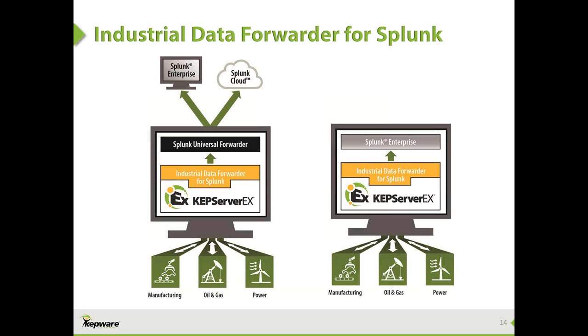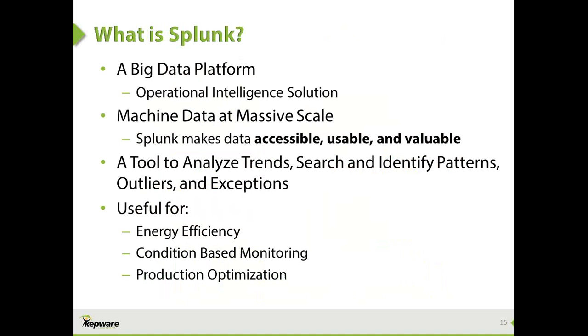So at this point, you're probably asking, well, what is this Splunk application anyway? Splunk is not part of KEPServerEX. It is another vendor, a third-party vendor that we're working with and collaborating with on this product. And it's a big data platform for that operational intelligence. It's for enterprise level, and this data can be collected from any source, making the data accessible, usable, and valuable. So that means using the IDF plugin, you can stream data from KEPServerEX into Splunk. And then it comes in via TCP port, and it will immediately start being collected and indexed.